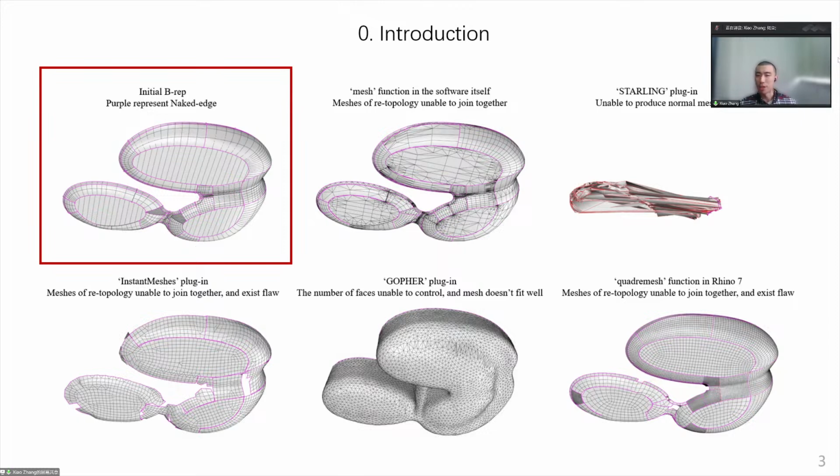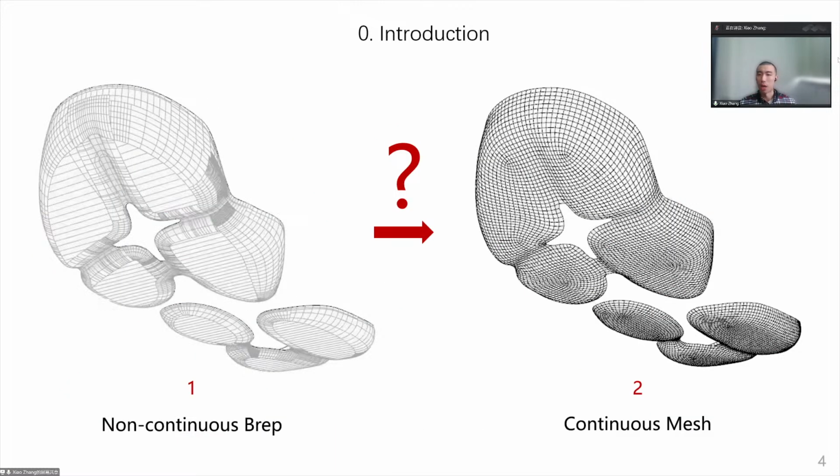Nowadays, there are many plugins in Grasshopper to help the transition work. However, many of them can just solve fine B-reps, which means they should be closed and the UV texture should be well joined and continuous. However, it is almost impossible to achieve that in shoe model work in reality nowadays. So we need to develop a method by ourselves to make a non-continuous B-rep into a well-continuous mesh, which means every face of the mesh should have a similar area to the neighbor one, just as shown in Figure 2.